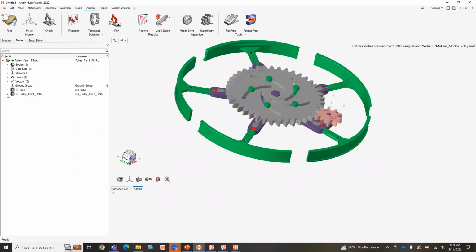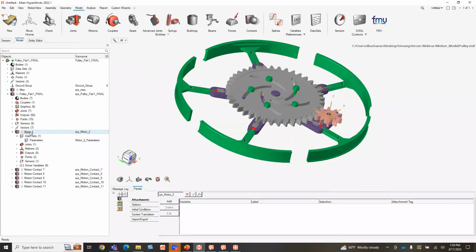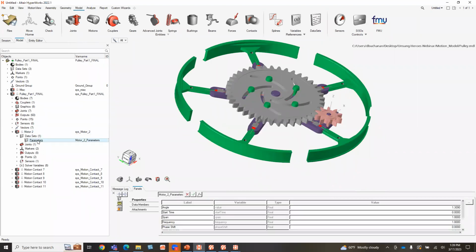You'll see in my system that everything in MotionSolve is set up around rigid body dynamic boundary conditions. We specify our joints, our motions, our forces, or even springs or bushings, and we can apply them. In this case, we have a motor being applied, and the motor you see right here is this pinion. You'll see I'm specifying about a 75-degree rotation here, in radians.